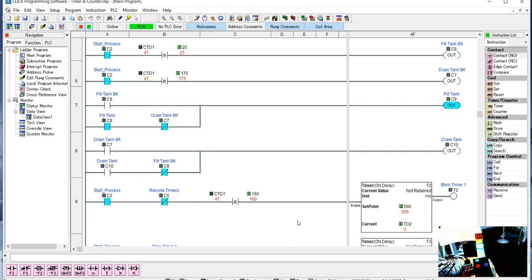And again, comparators are used all the time. When we get this comparator, we're going to use our seal-in circuit, and our seal-in circuit is invaluable for when we want to hold it, because this condition is only here temporarily and then it goes away, but we have to latch it in, we have to seal it in. So we have comparators and they work with the seal-in circuits.